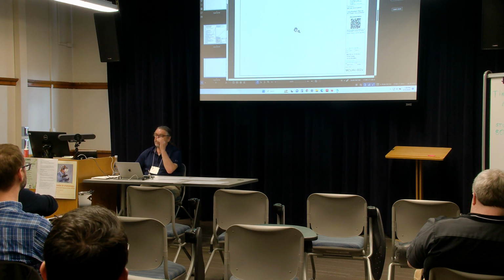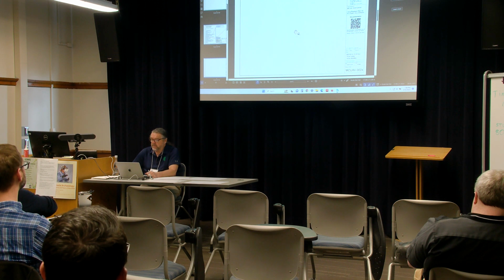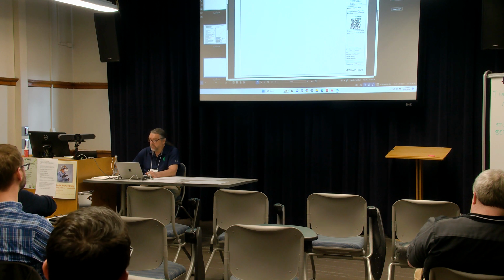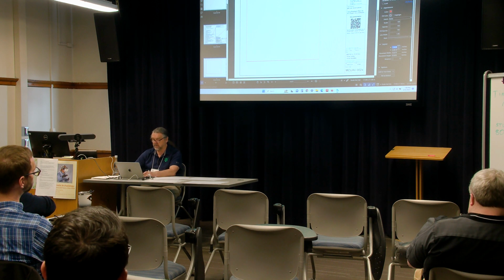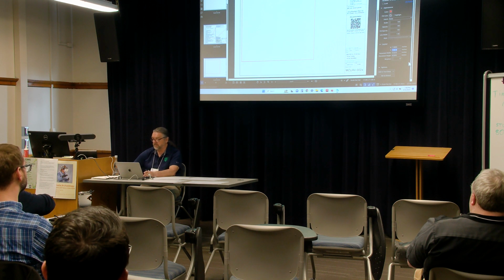One of the things I wanted to do was have a decent looking title block. And this happens to be for 17 by 11 paper. And one of the cool things about Bluebeam is that I can take an object like this rectangle, and if I draw this rectangle over here, which might be hard to read, it tells me the starting point of that rectangle is at 1.6 inches. I'm going to change that to 1.0. And you just saw it move over. And then I'll change the y coordinate.